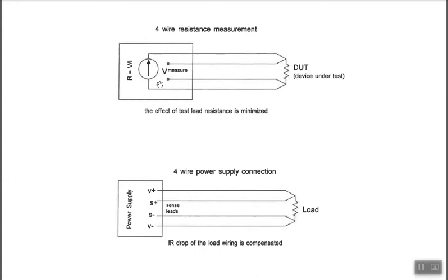Very simply, you can have an ohm meter. All ohm meters do is send out a constant current and read the voltage and then use Ohm's law. So they'll send a small current through whatever you're trying to measure, and then measure the voltage that develops across it. But the problem, of course, is you don't want to include the voltage across your test lead wires. So you do the same thing that we saw with the 4-wire RTD. And in fact, highly accurate ohm meters that are able to measure very low resistances, this is what they're going to do.